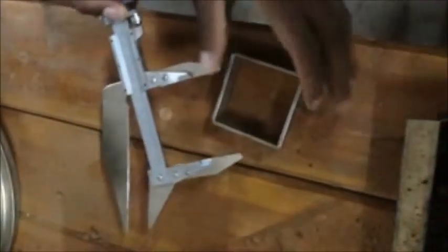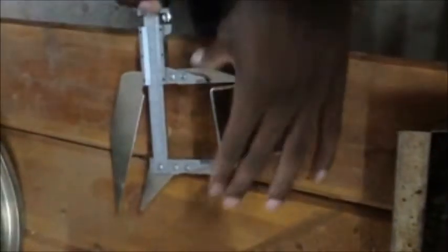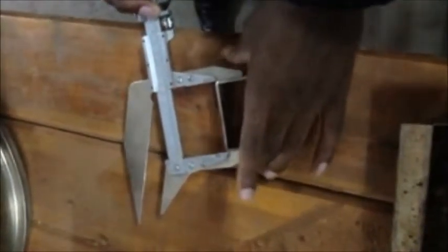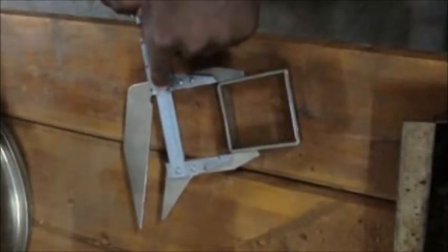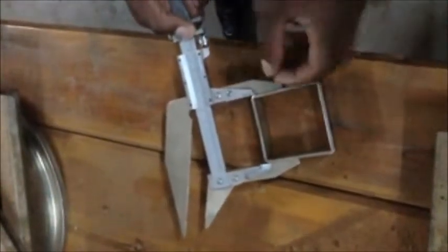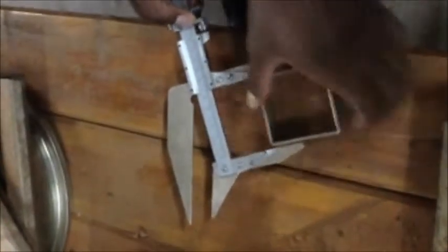This is the way of determining the height of the sampler by using a vernier caliper. It has graduations in millimeters, so you convert it to centimeters. This is the way of measuring the width. After getting those dimensions, we will be able to determine the area, and after determining the area, the volume. After getting the volume, we will be able to find the density of the soil, because we will know the mass of the soil.